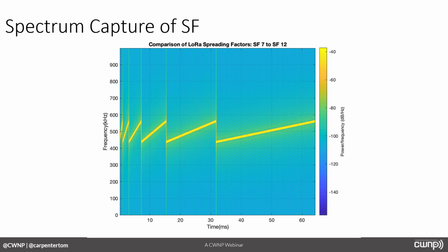Now, the thing is then that the wider the spreading factor, the lower the data rate, but the higher the resiliency. And that's why as we have a wider spreading factor or a higher spreading factor, because it's really not wider, it's spread over time. So a longer spreading factor is the word I should be using there. The higher value or longer spreading factor gives us more resiliency because it's slower, right? It's a good way to think of it.